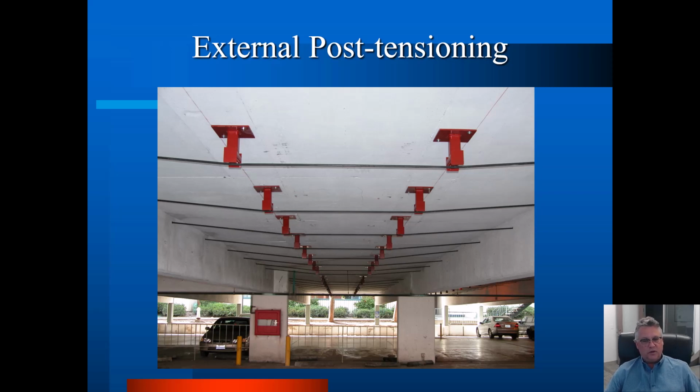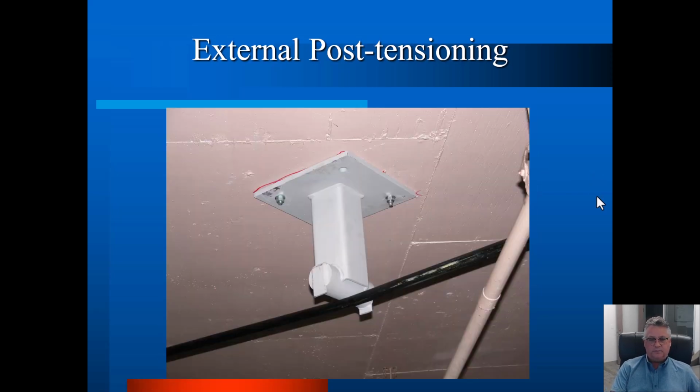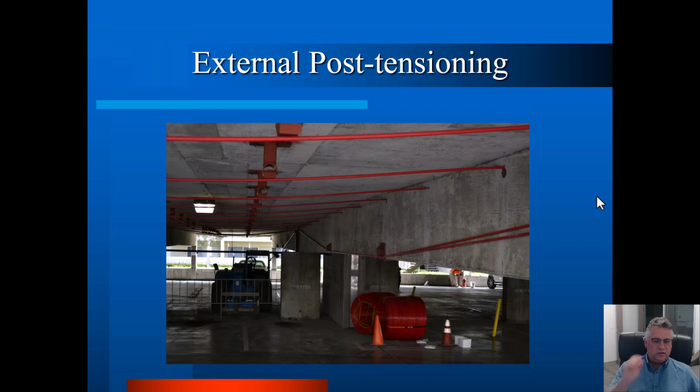The salt air came in every morning, deposits a marine layer down, and it's just eating away at the post-tensioning that's up there. We replaced it using galvanized tendons in sheathing from below. So it still stands today. It's one of our favorite jobs. Every once in a while we'll take students to this job. External post-tensioning is just a terrific, lightweight, very strong way to fix a building.